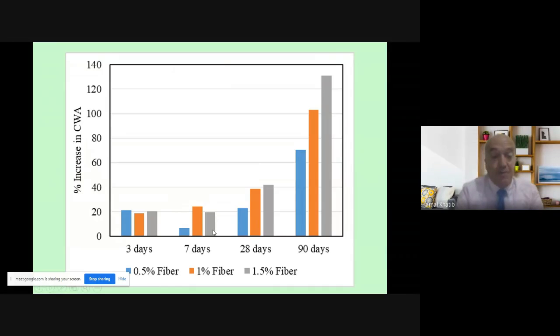And of course, the capillary water absorption test is quite sensitive. We remove the sample each time, then put it back, and you need to dry the sample. You have to be very consistent in the way you do things.